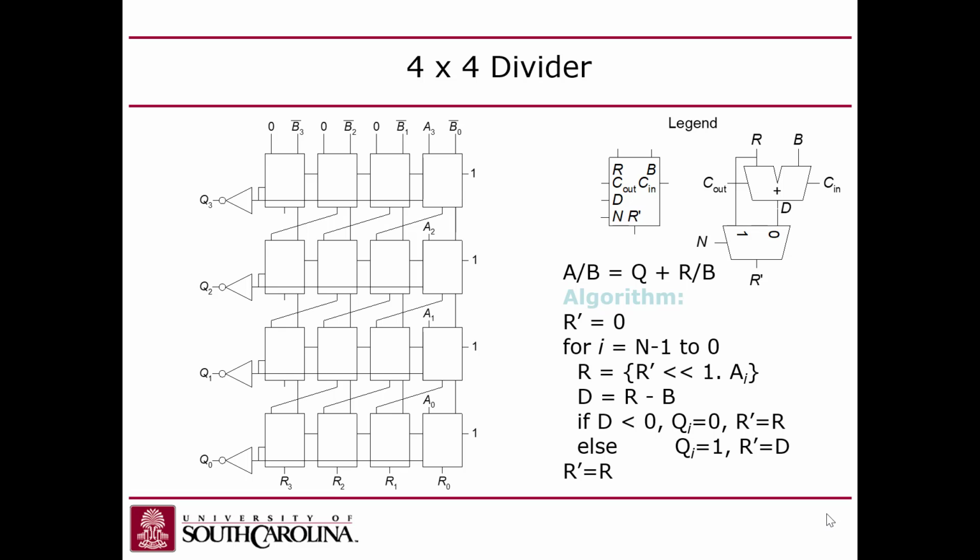So then they take the result. The result of that is these bits coming out of these adders, and that's going to be the new remainder value, which may or may not be negative. If it's negative, they have to restore it back to the original form. That's why they use boxes here, because inside this box they have this pseudocode. Basically what this is saying is that if the result is less than 0, then they restore the original value that's coming in.